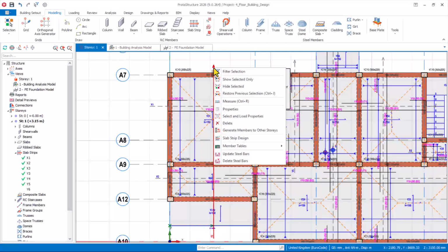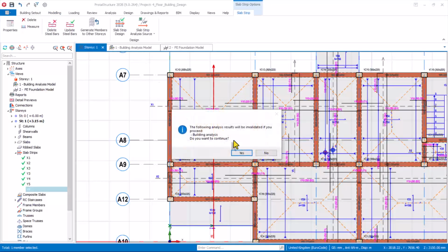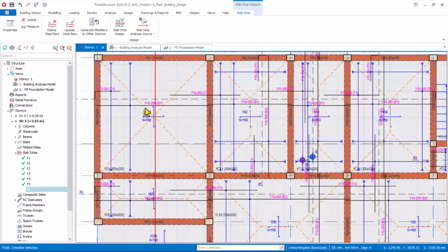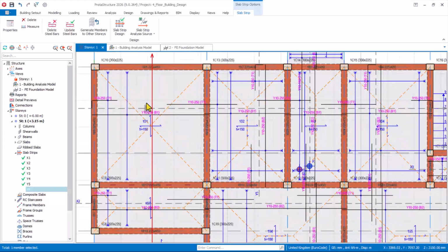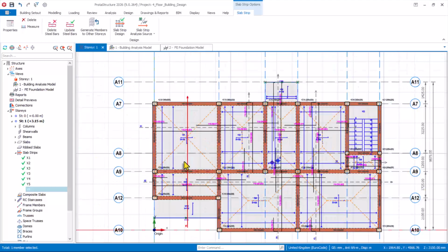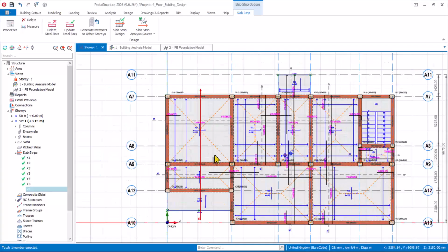So once it happens like this, what you just have to do is to increase the slab thickness. I don't want to nullify this analysis. All right, so just increase the slab thickness. All right, and then we run the strips again. It will pass. And then you have to take note of this particular panel during constructions to ensure that it's being implemented properly. All right, because it is actually falling in the y direction. You see the x direction strips has passed successfully.